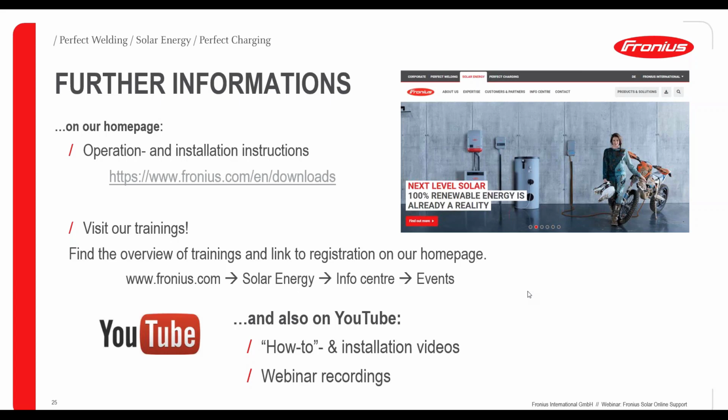The next question we received is whether there are overvoltage protections available, so what about lightning protection of the Tauro device? That's also a very good question. It was not the topic of this webinar, but of course we can gladly answer it. Lightning protection is installed as standard. We have surge protection devices on the DC and the AC side integrated as standard, so type 1 and 2 are integrated here.